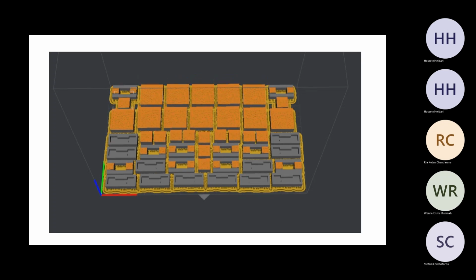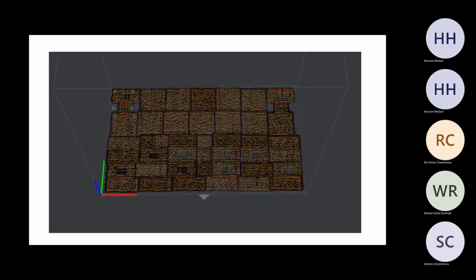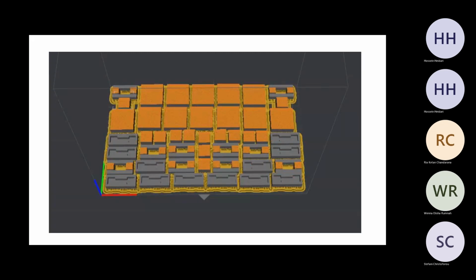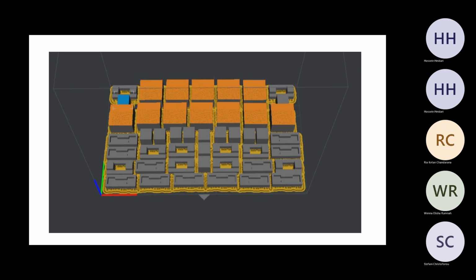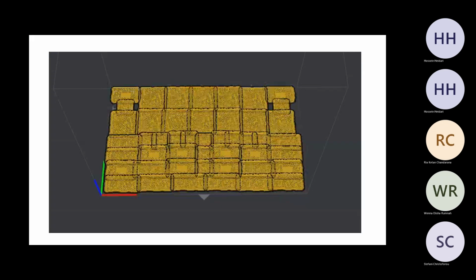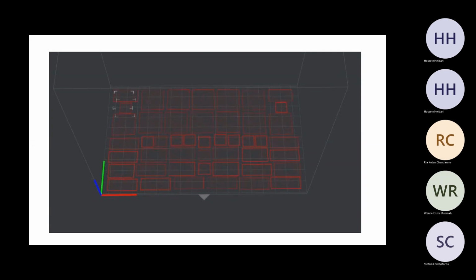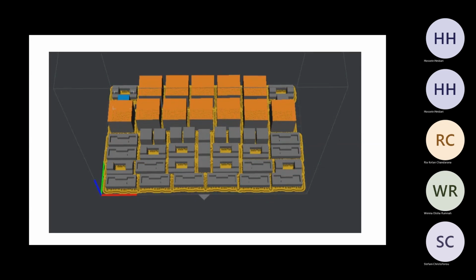But fortunately, we got to slice them in time, in about 5 to 10 minutes, and then generate a new design and start everything over. And then I basically reduced the size of the objects a little bit, but then I made these branches a bit longer. So the optimization here is a big deal. Okay, the amount of time you spend per layer can be the reason you have delamination, can be the reason that you have rough edges. It may potentially not show up immediately after, but as you come back in week 12, you'll see that it has completely destroyed the structure, it's completely disintegrated because you didn't have proper interlayer bonding.